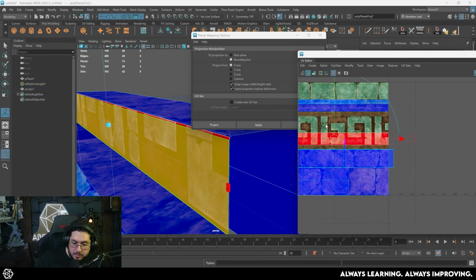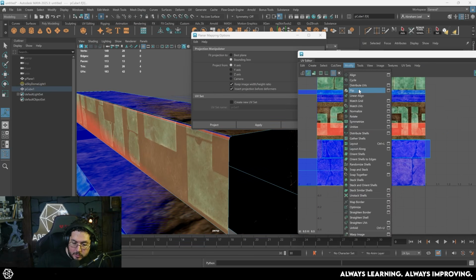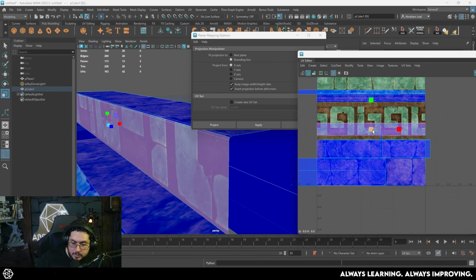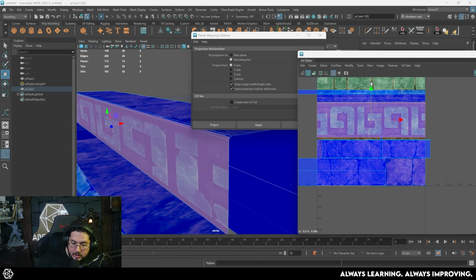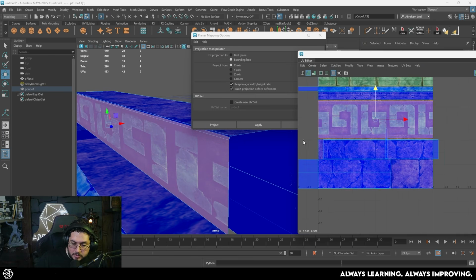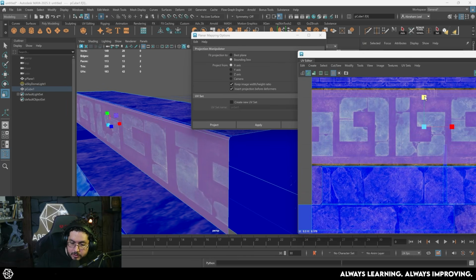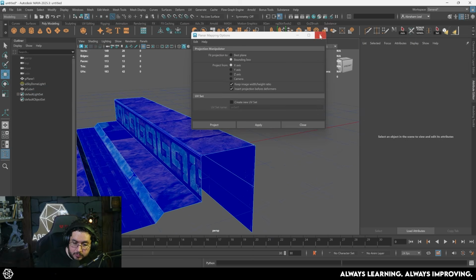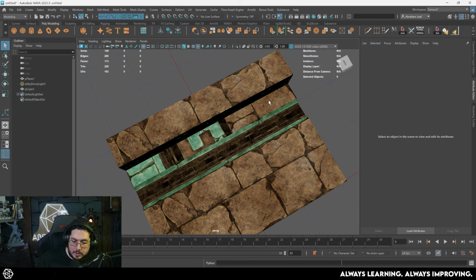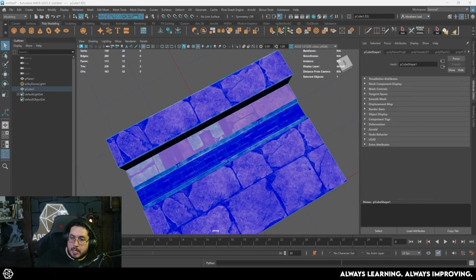As you can see, this mapping is from the x-axis. We need to flip the UV so that it's proper here. And now, first I'm gonna scale here on the x-axis to capture the range of the elements properly. And then I'm gonna use the scale on the U element right there. That gives me a proper distribution of the whole thing. We do another planar mapping on this final island that we have right here.